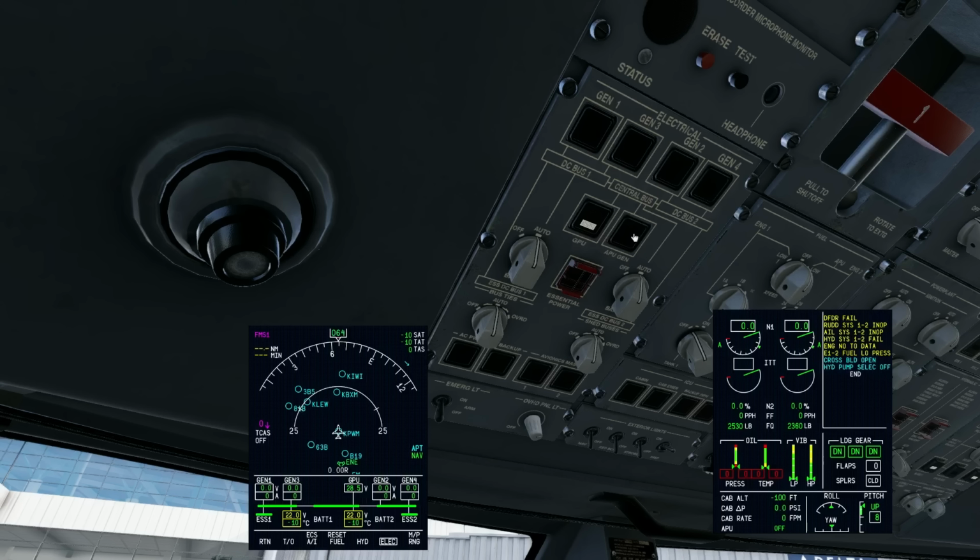In the same vein, we don't have the APU on, but for example, if I were to deselect the APU push button, the APU is a little bit of a different one. This button lives in the in position. The reason being is that the electrical logic is going to switch through generators, the APU gen or the 4 engine-driven generators, as required based on the situation. So taking the APU out of the mix, hard deselecting it from the EDL, the electrical distribution logic, is a non-normal thing. We're basically bypassing the automatic electrical control system. So we leave that in, giving the computers the ability to basically command whatever generator they want.